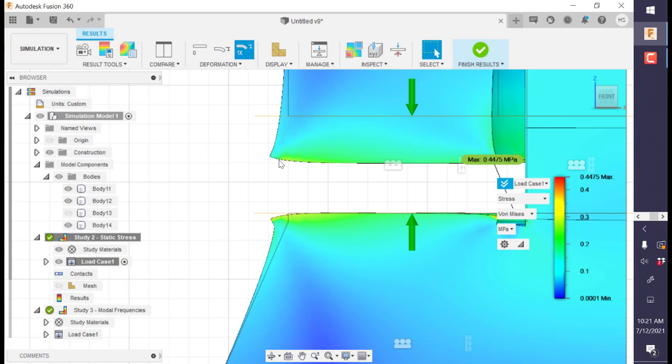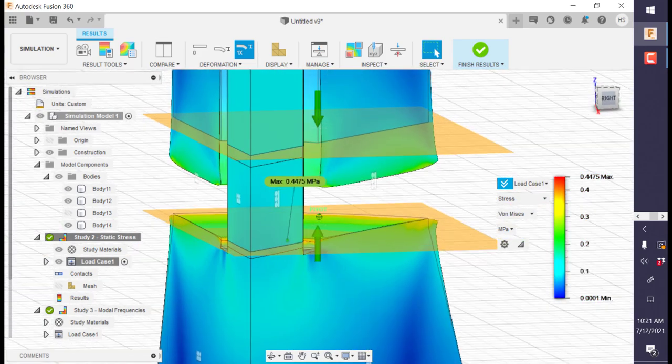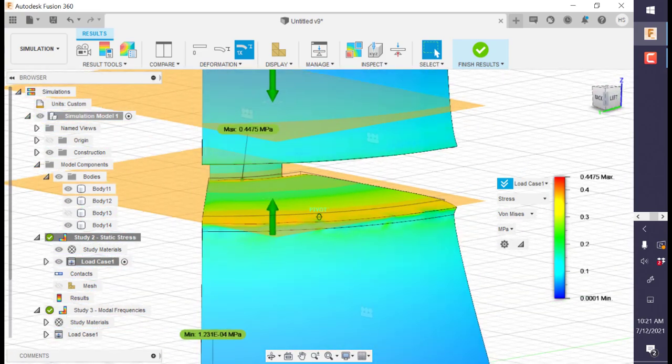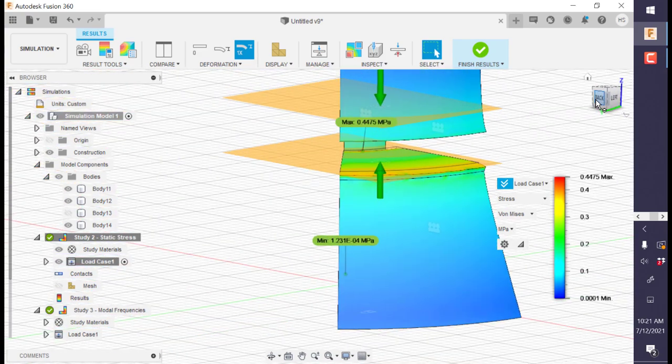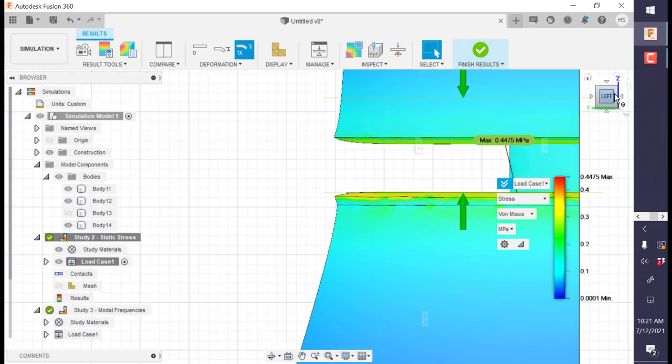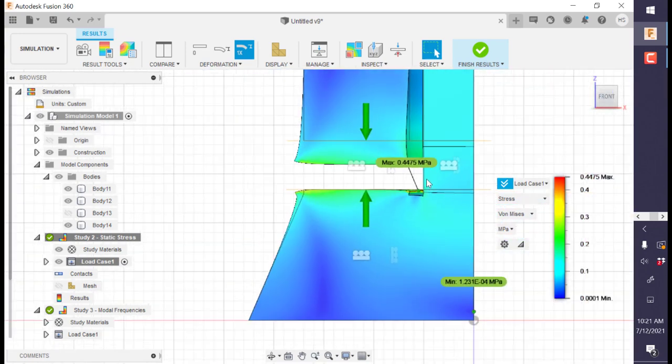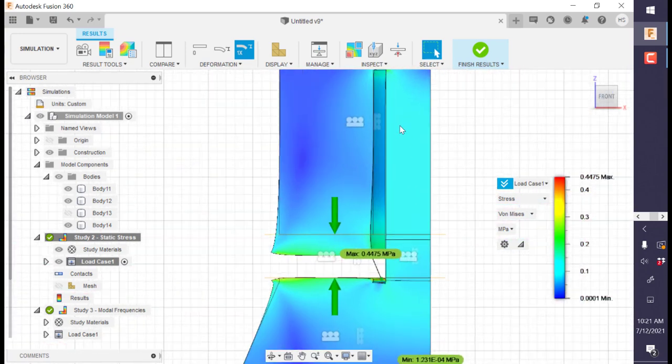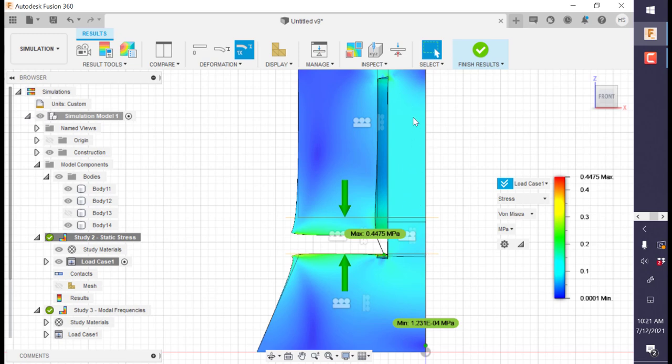So there's a significant amount of stress and deformation right around the piezo, which is obviously expected here. So it's not completely clamping. Additionally, you see we have a static stress being generated inside of the center bolt. So when the piezo expands, it's going to expand the center bolt. When the piezo contracts, the center bolt is going to go under more compression.